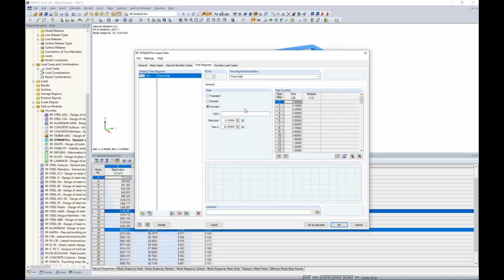And finally, there is the ability to input in a function. So we can actually define variables and parameters. This would be extremely useful if we were taking the more theoretical approach for the idealized pressure time history curve. So for example, the Friedlander equation, we could actually input in. So we do have some additional resources here that I can relay to you if you are interested in seeing that more theoretical approach with this function option. So just reach out to us if you are interested in that.